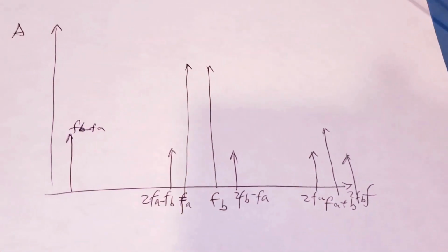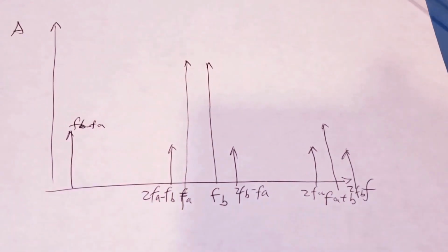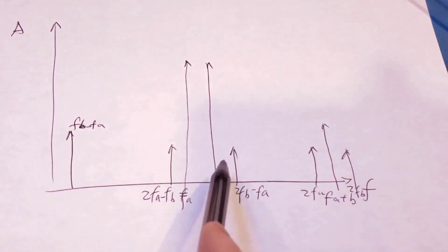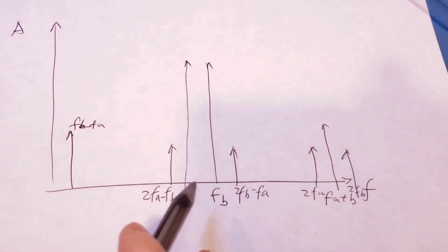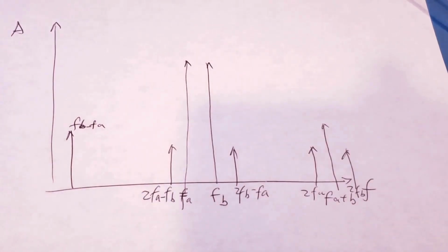So let's actually come back to our diagram here. The close proximity of these signals is obviously one issue, but here's another issue. As the amplitude of the fundamental frequency increases, so do the amplitudes of the third-order products. And because these are third-order products, the slope is 3 times that of the fundamental tone, because the third order is a cubic function. So if you take the log of that, you get a slope of 3. Why is this a problem?